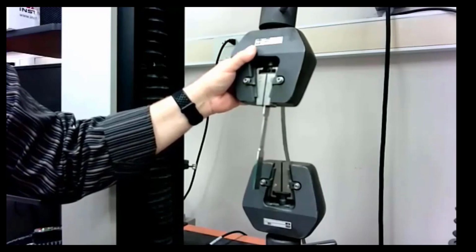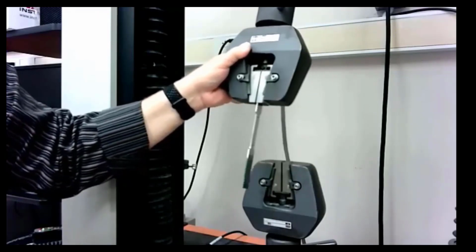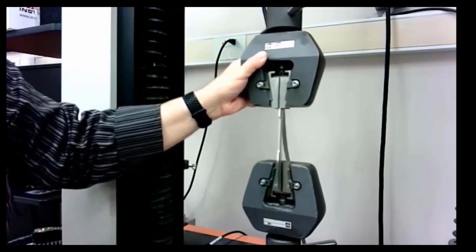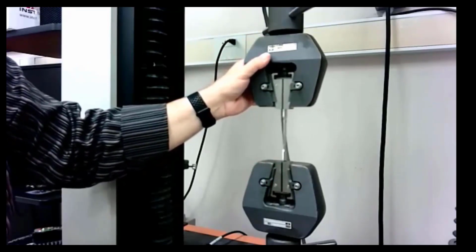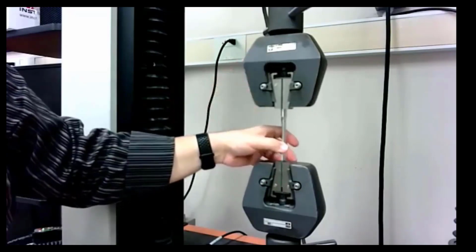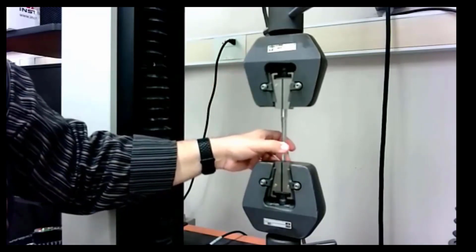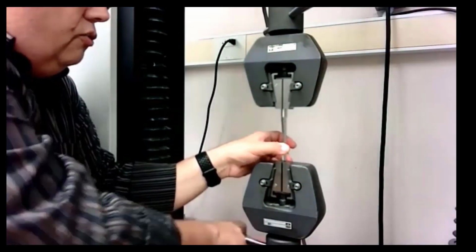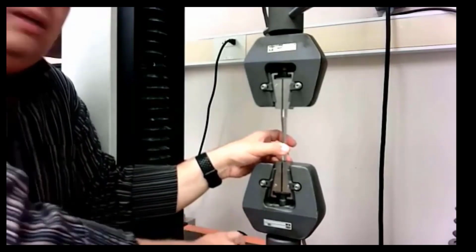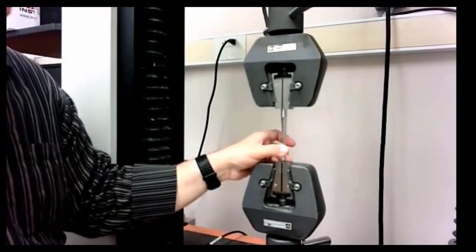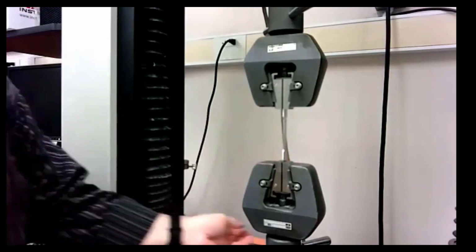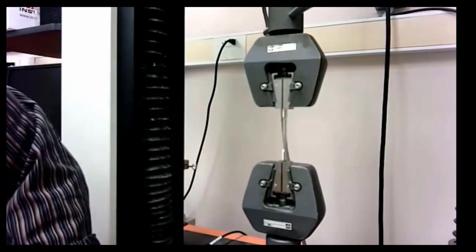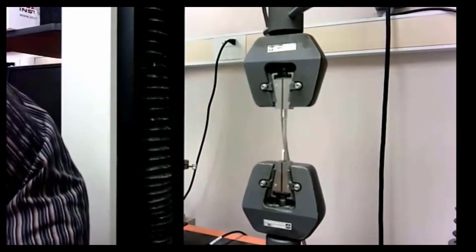We're always going to start with the upper jaw because that's the one that has the universal joint in it. And when we unload, we'll do it in the reverse order. Now I can slip the bottom half of the specimen into the lower jaw, hold it gently against that backing plate in the lower jaw just with one finger, and this screw feels backwards because it's upside down. Again, I get it snug, I let go of the specimen, and then I can finish tightening that down. Now we're ready to install the extensometer.